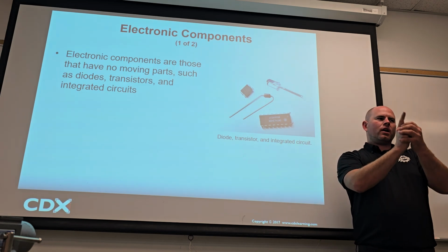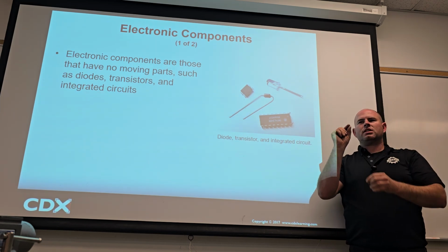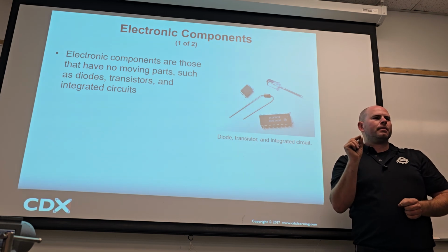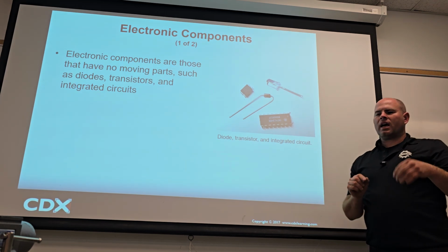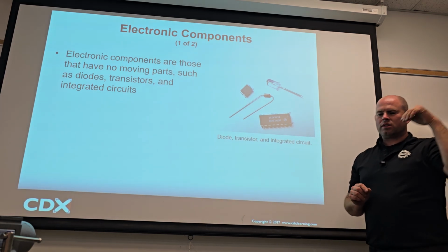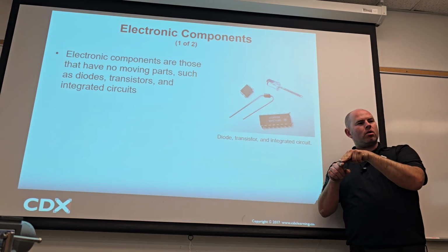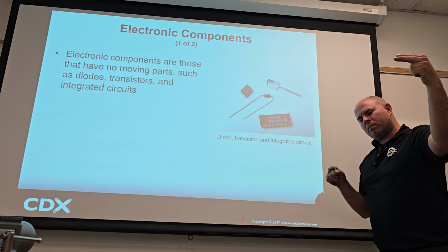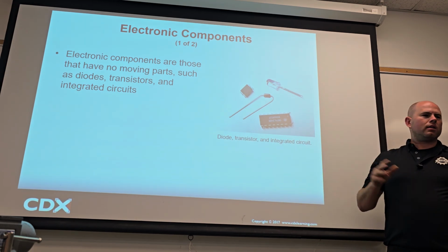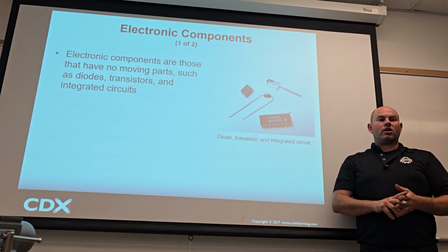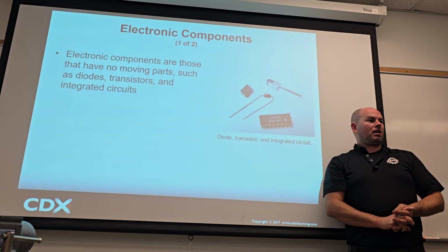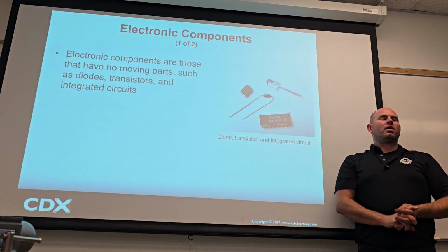Then the one wire, all it does is send a pulsed signal back to the ECM. If I can verify the sensor's getting 12 volts, the sensor's getting ground, the sensor's giving that pulse, and that pulse is making it all the way back to the ECU, then I can know everything I need to know. As far as the transistors in the chip, I can't even process that information.